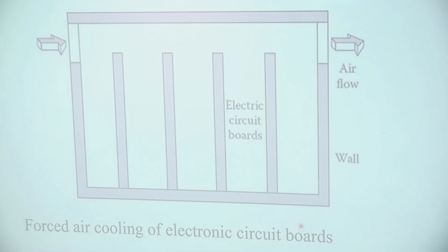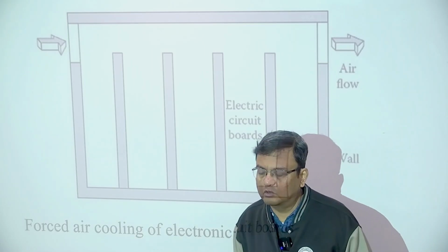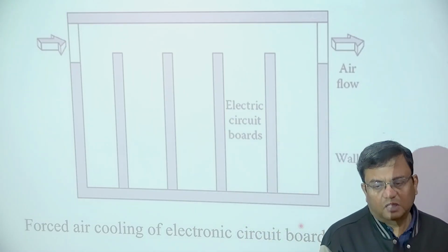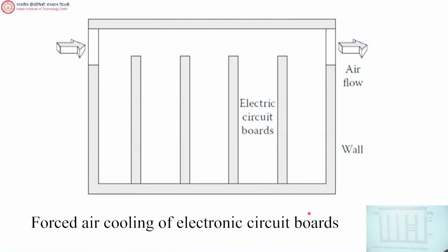Ultimately, our objective is, remember, to limit the temperature of the electronic components to some reasonable value up to which it can perform properly. Right? Yesterday I mentioned 80 degrees Celsius. I just said 80 degrees Celsius. It doesn't have to be 80 degrees Celsius. It can operate maybe at 115 also. It depends on the particular circumstances of the particular setup that we are talking about.